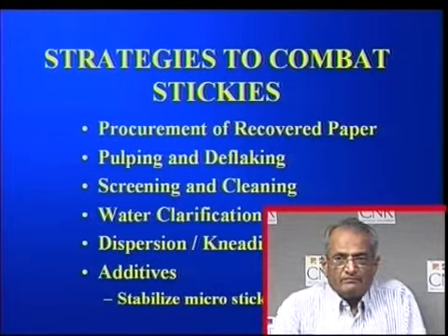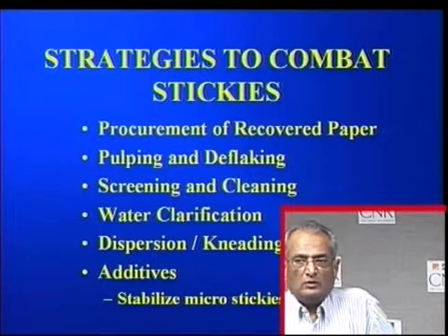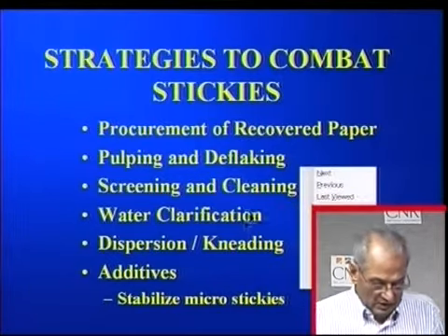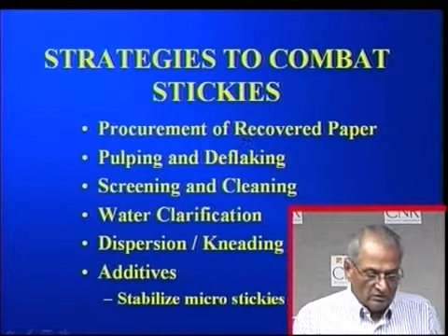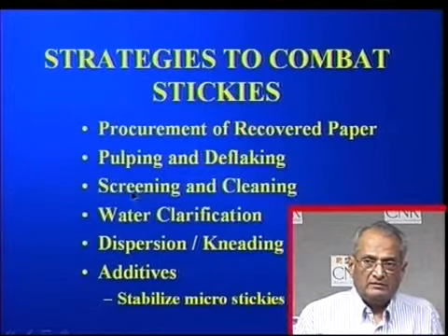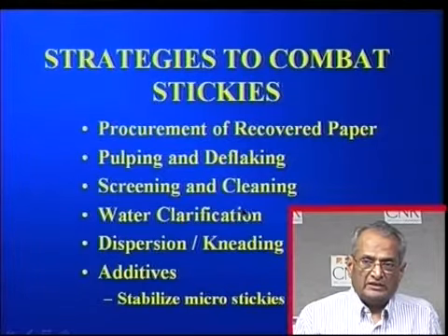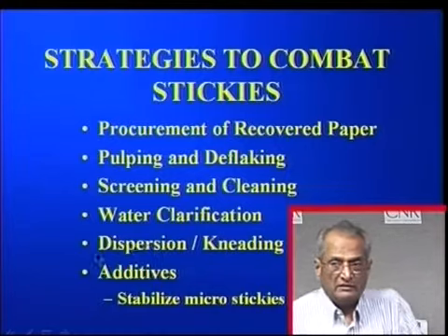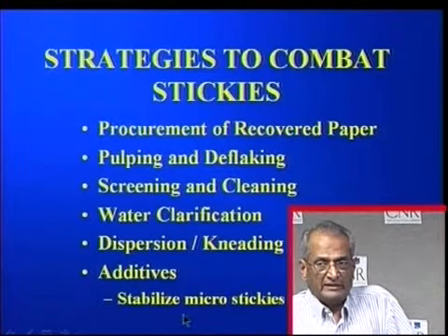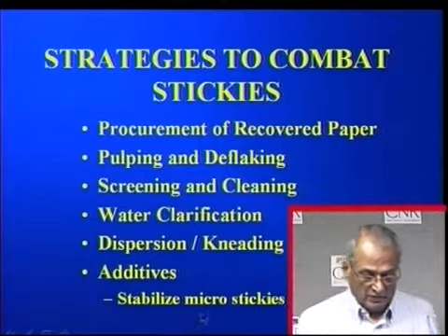So several strategies for combating the problems caused by stickies include proper selection of the recovered paper, gentle pulping and deflaking, proper design of screening and cleaning system, effective water clarification, dispersion and kneading if needed, and finally additives to stabilize micro stickies.